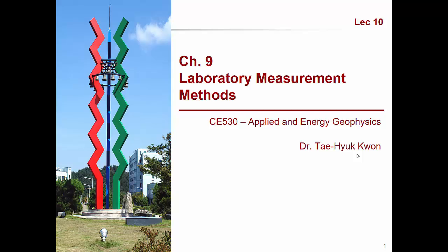The reason that we are doing experiments is to find out the property, or could be to determine the engineering property of the rock and soil. Another reason could be that we want to know what's going on inside the soil, inside the pore, or in the skeleton. So we can use the P and S wave and analyze the velocity and the attenuation, and we can use that parameter as an indicator of the internal process in the soil.